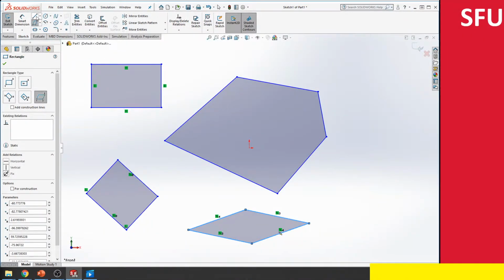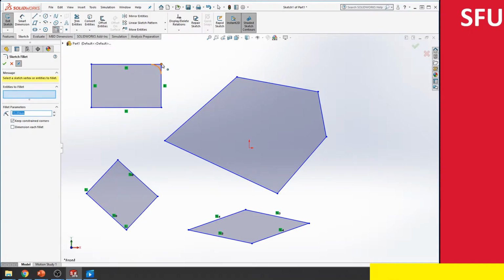But this gives you an option because you're going to be using fillet fairly commonly, very regularly. So it gives you an option to quickly create the fillet. In order to do that, you click on this fillet tool, and then you can click on this corner over here, and then it automatically picks up the fillet and creates a fillet of a radius 10 millimeters.